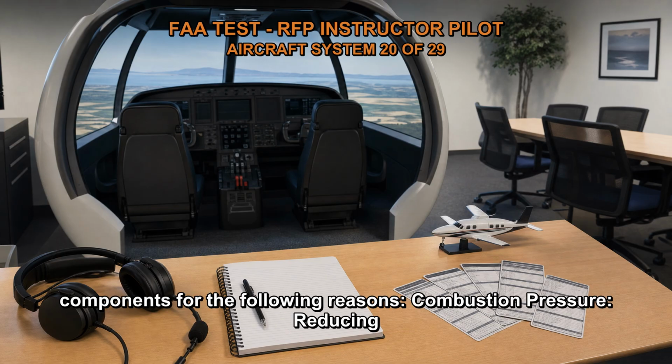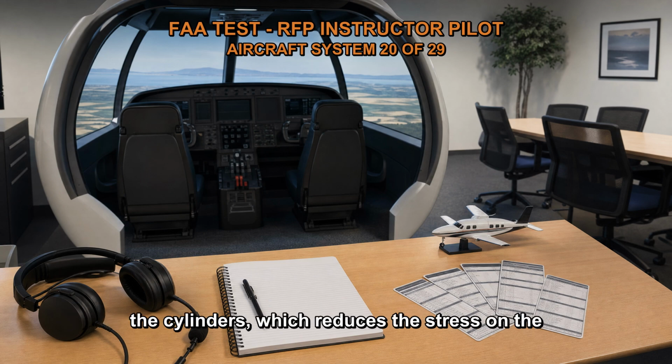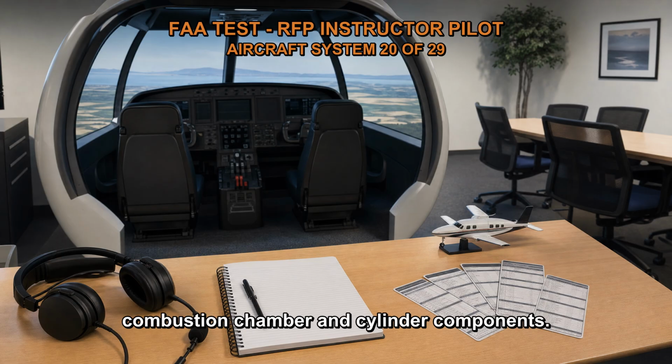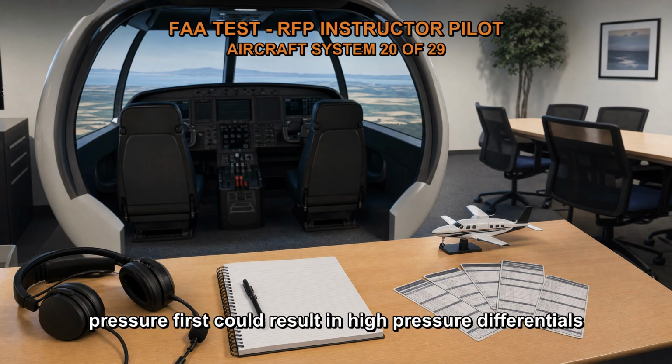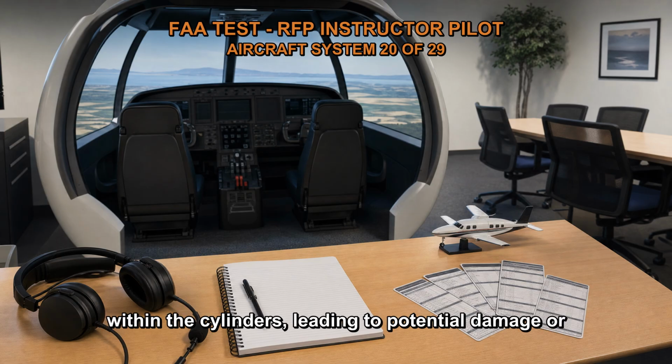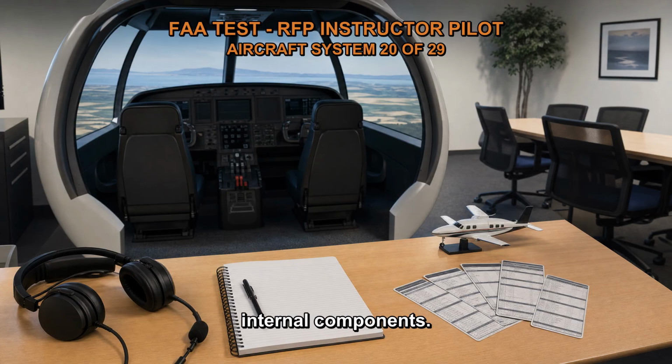Combustion pressure. Reducing manifold pressure before RPM decreases the pressure within the cylinders, which reduces the stress on the combustion chamber and cylinder components. The sudden reduction of power without reducing manifold pressure first could result in high-pressure differentials within the cylinders, leading to potential damage or stress on piston rings, cylinder walls, and other internal components.